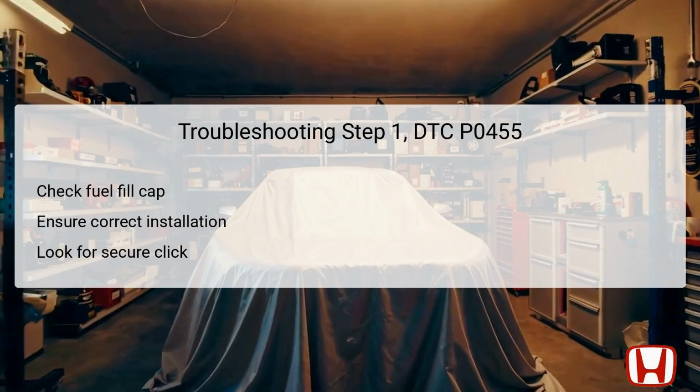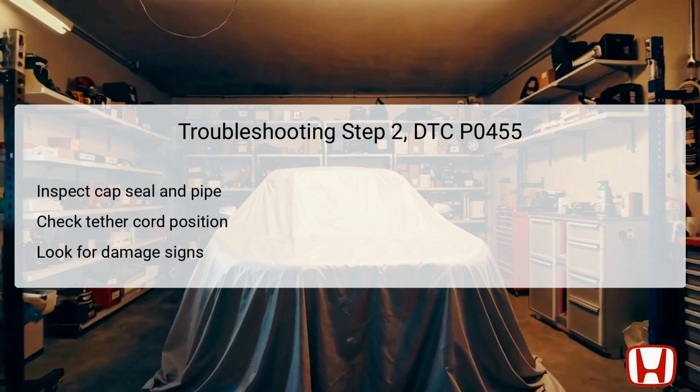If the cap is found to be loose or damaged, it can allow fuel vapors to escape, triggering the DTC. If the cap is not secure, tighten it, and then proceed to further diagnostic steps to determine if this resolves the issue.